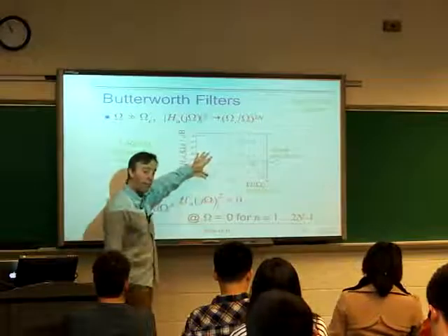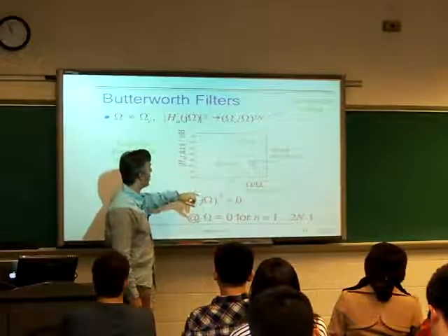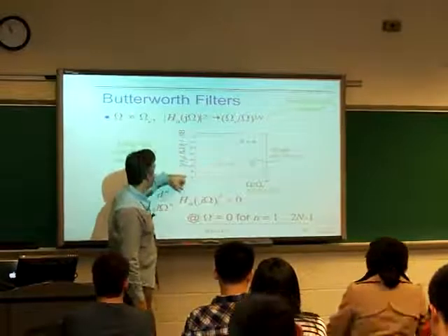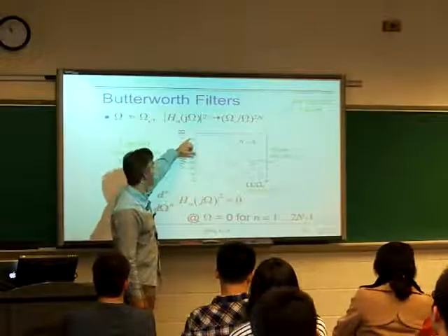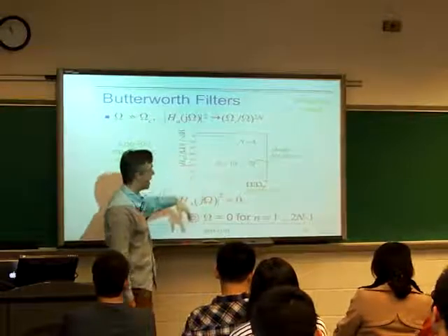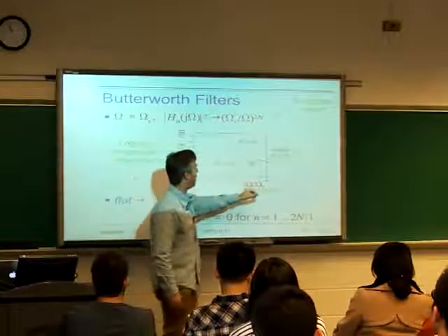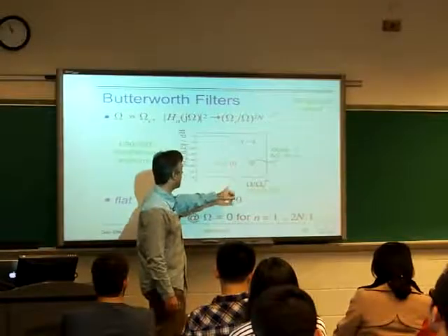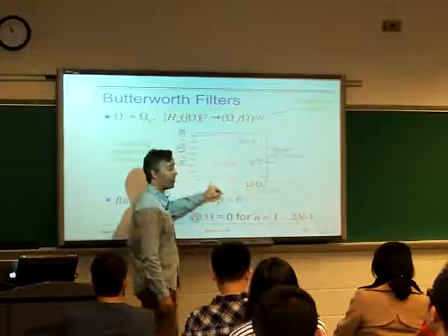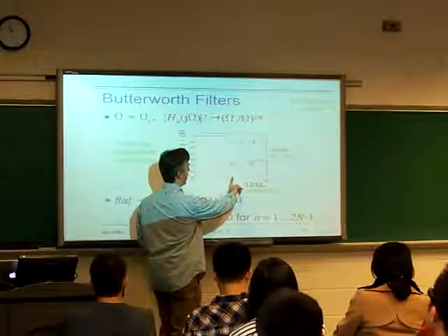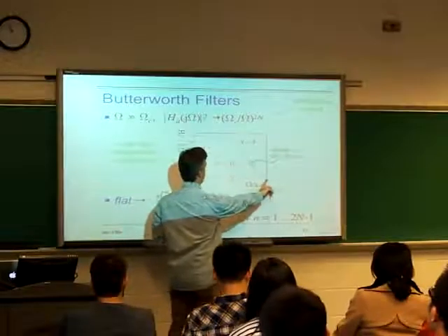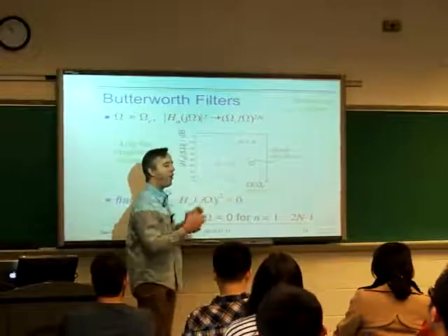So this is the same plot, but now I'm plotting it as a log-log plot. The magnitude axis is in dB, so it goes to 0 and then goes down to negative infinity. And the frequency axis, the analog frequency axis, is still omega and omega c, but it's on a log scale. So here's omega equals omega c, 10 times, and 1/10.